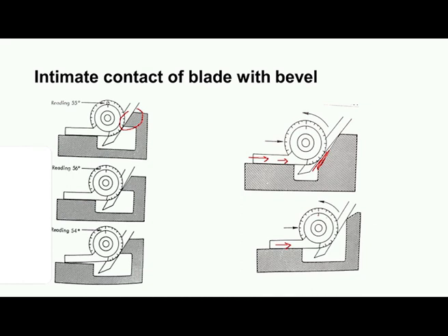So, while using this bevel protractor, the surfaces of the workpiece should be properly cleaned, and surface of the blades of the protractor, bevel protractor should be properly cleaned, and then we should carefully use the instrument. Now, we will conduct a simple experiment to learn how to use a protractor.